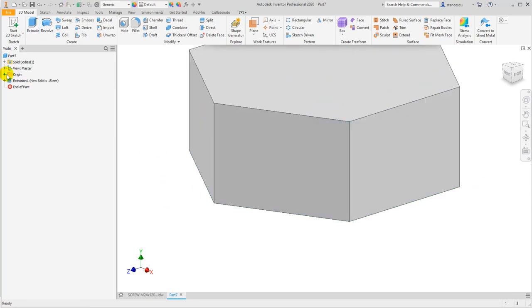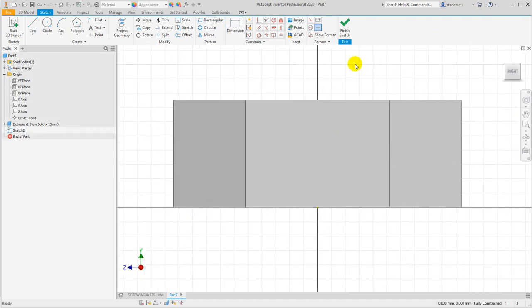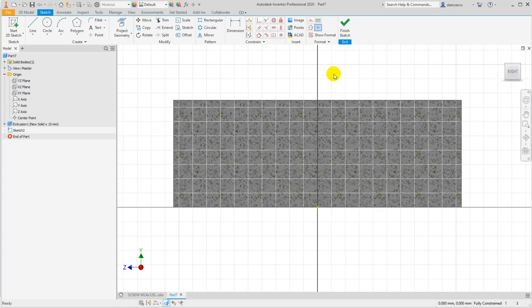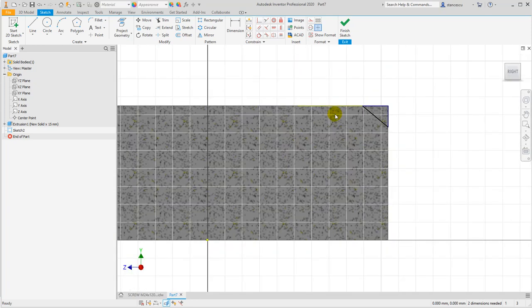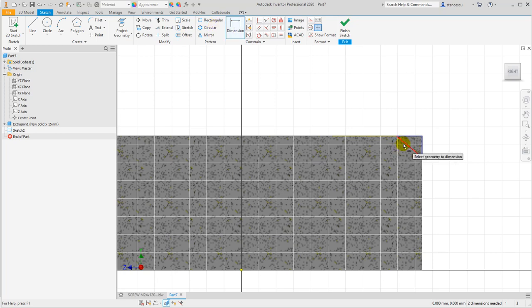Okay, and now we use the plane diagonal. We project constructive this edge. We disable constructive, F7, Foxtrot 7 to see inside, and we draw a triangle here in order to make the chamfer. Good. I hope everything is okay. Good. The angle from here is 60,